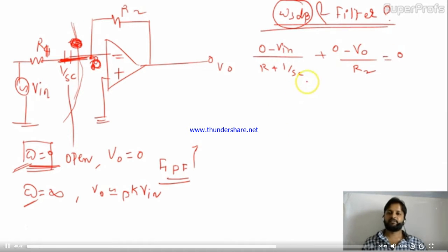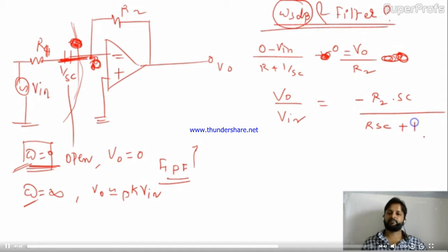Finally you take this to that side, and V naught by Vin will be minus R2 SC divided by RSC plus 1.